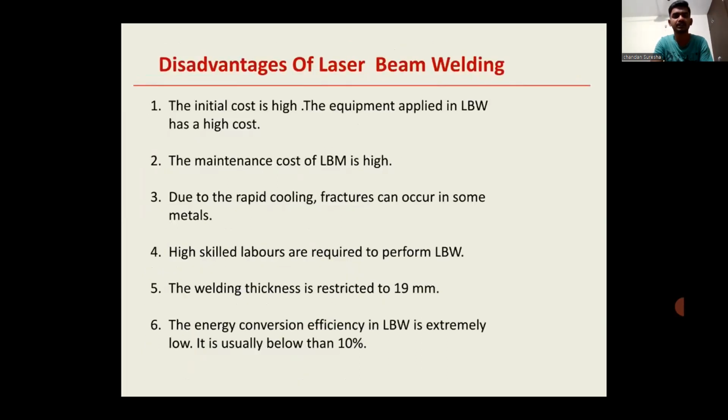Disadvantages of laser beam welding: the initial cost is high, the equipment is costly, the maintenance of the laser beam machine is high, and due to rapid cooling, cracks can occur in some metals. Highly skilled labor is required to perform laser beam welding. The welding thickness is restricted to 19 mm. The energy conversion efficiency in laser beam welding is extremely low, usually below 10%.